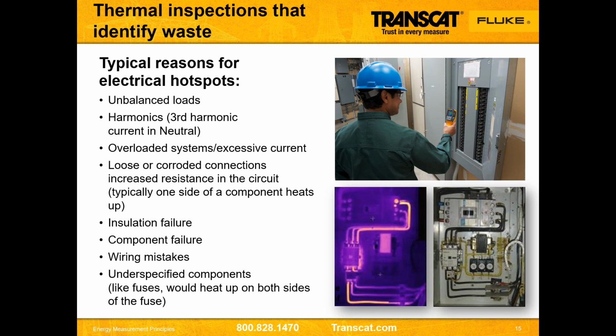Reading something with a thermal imager, which is a great tool, will tell me that it's hot, but it won't tell me why. So we want to investigate other methods of measuring these, either with a voltmeter and/or clamp-on, but potentially in many instances, I'd like to use a three-phase power analyzer to look across all three phases to figure out why it is hot. Then we start to uncover problems, like they're unbalanced. The voltages and the currents on each phase are not the same. And if they're more than 10% unbalanced, you're going to have some problems within your plant, because a lot of the loads and devices will not like that and will not work very well.